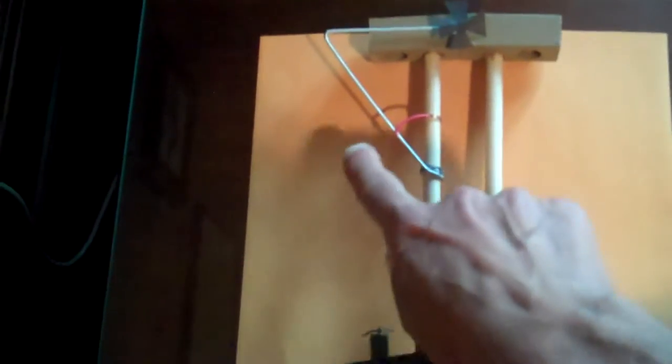The cross trail is equal to the trail, which we have entered from the tables, times the sine of the drift angle which has been established into the wind. Therefore, setting the trail allows the bomb sight to adjust for both trail and cross trail once the drift angle is established.